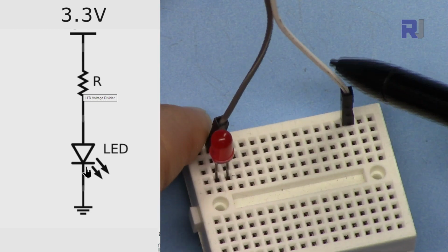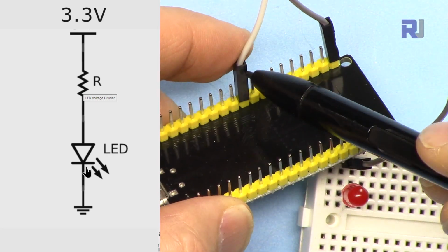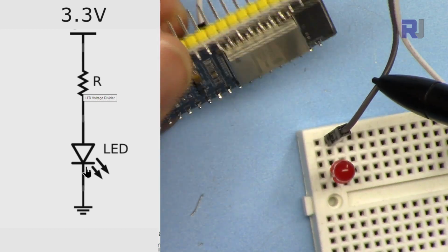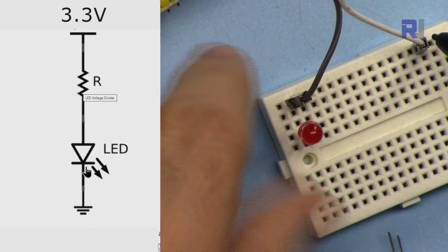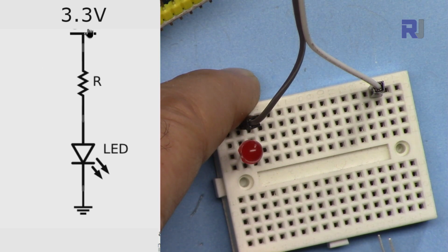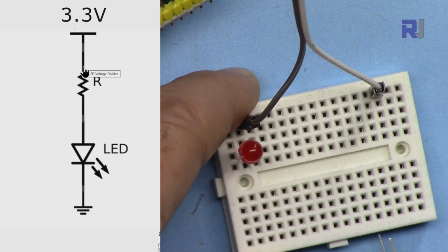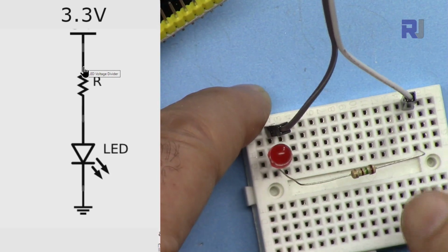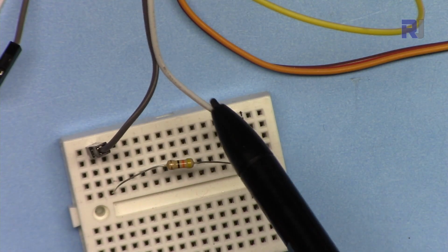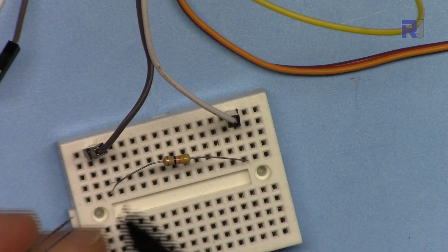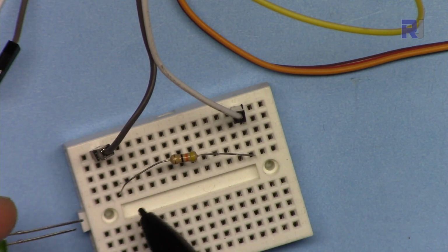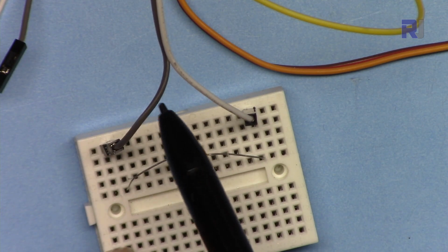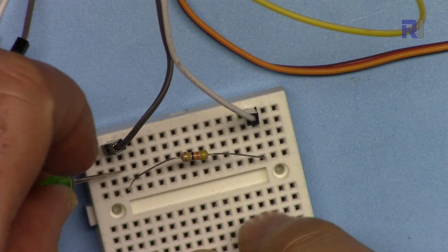Here the positive comes, this is connected to pin 5 of my ESP32. It says G5, and the other side is connected to the ground, or GND. So assume this is my pin 5, 3.3 volts comes, and then I have here a 150 ohm resistor. I'm supposed to put here 130 ohm for one LED, but I don't have it in hand. This pin goes to pin 5 or G5, and then a resistor, and then the longer pin of the LED goes towards the resistor on this line, and the shorter pin on this line goes to the ground. So I'm inserting the longer pin on this side, like this.